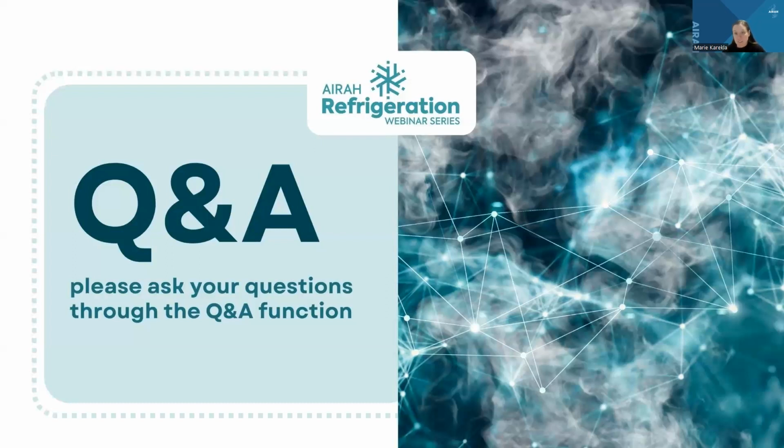On large refrigerated warehouses, obviously, as I say, ammonia, and now I think CO2 in some cases, but we really haven't seen any large cold store here using CO2. I've seen it in New Zealand using CO2. And now ammonia for big cold stores is low charge ammonia, which can have a niche market there.